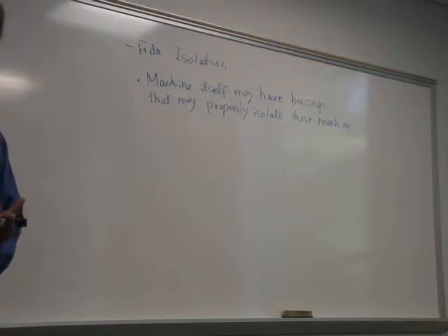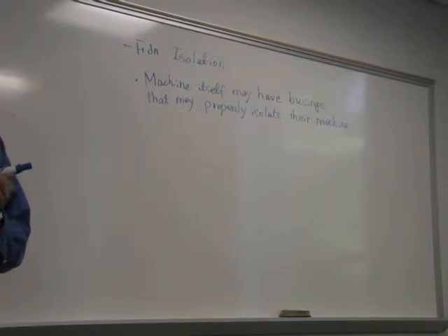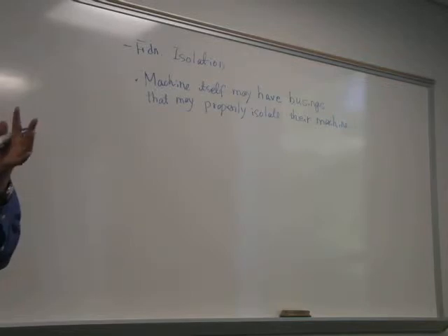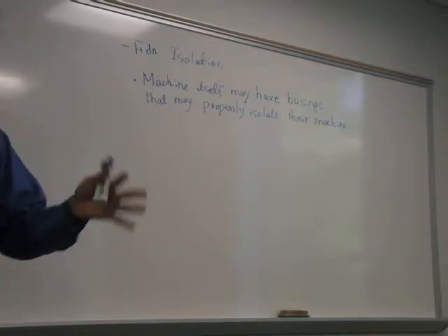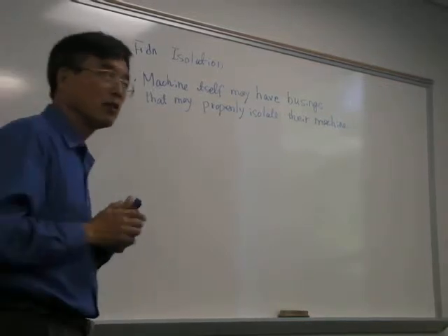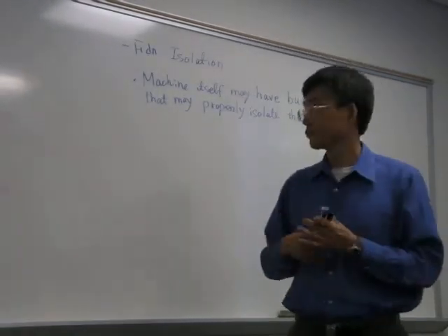The reason is engine mounts. Typically we have rubber pads for the engine mount and transmission mount. That means those engines and transmissions are not really directly connected to the body or frame. So they vibrate, but the vibration is limited on those engines and transmissions.